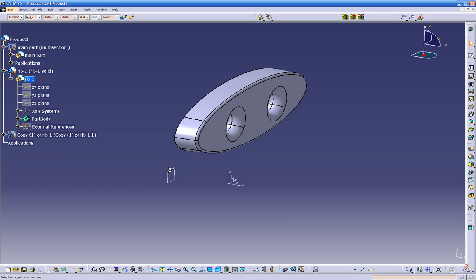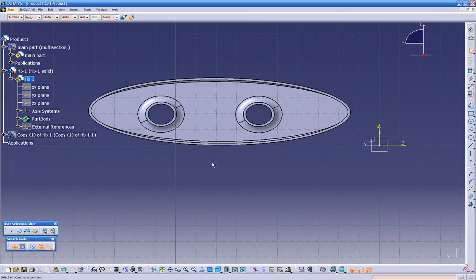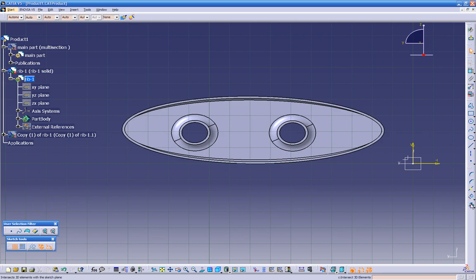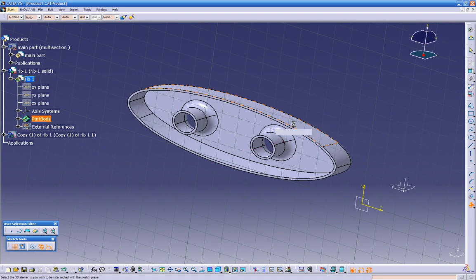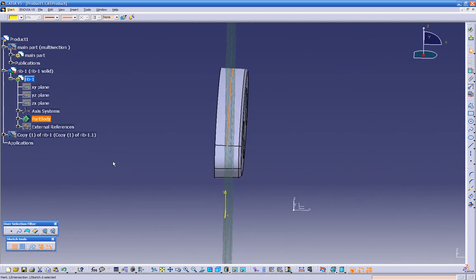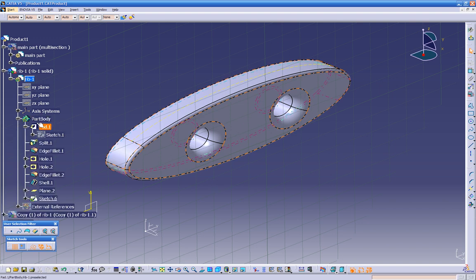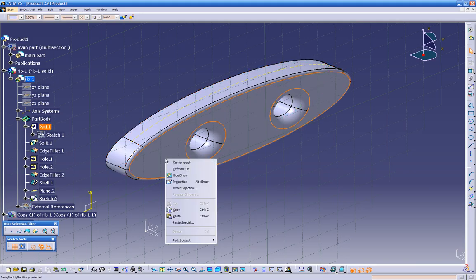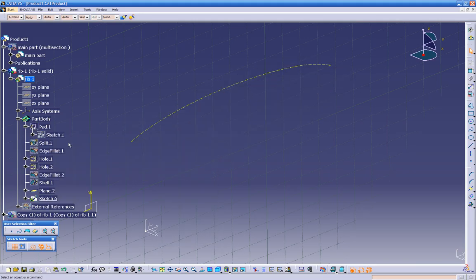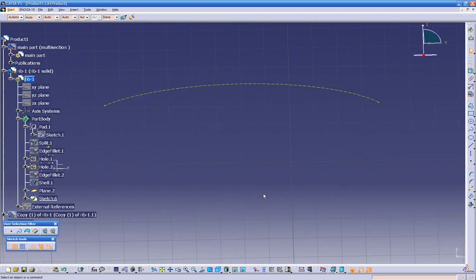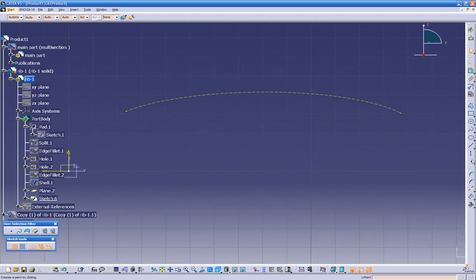Okay, so let's open a sketch, and let's go back again to this 3D elements intersect, and we have our curve over there. We have to make sure we turn this option off. Let's hide the body. Let's see if we can get from here. Okay, let's do normal to view, and let's put a couple of points. We use adjustable at equidistant points.